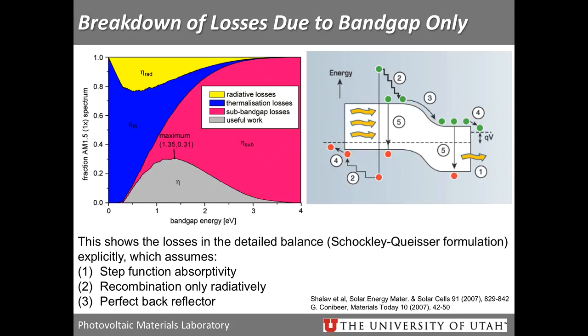If you have defect states that present energy levels within the band gap, so essentially allowable energy levels within this forbidden gap, you can have recombination via intermediate states that don't emit photons. So essentially, they emit phonons. They just go to heating the solar cell. So this idealized version says that if we're going to have recombination, it's going to emit a photon, and that can be reabsorbed by the bulk.